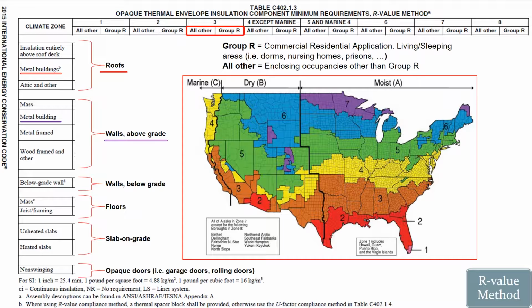And so that would be insulation entirely above deck. So that category could be used even though you have your typical tapered rigid frames and your common purlins and girts for the walls. However, if you get out of that purlined area, you would investigate what's within the insulation entirely above deck.